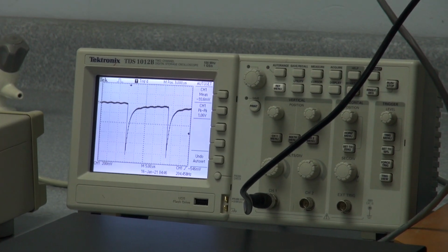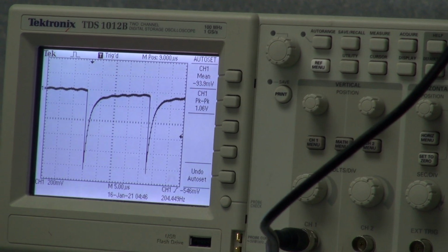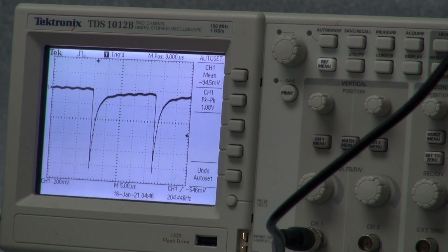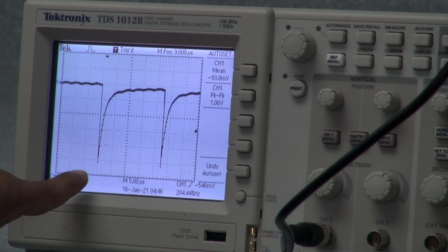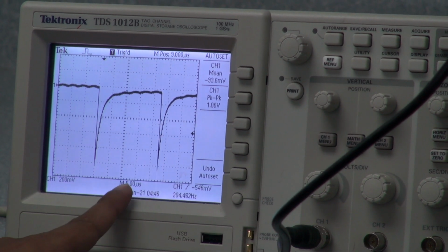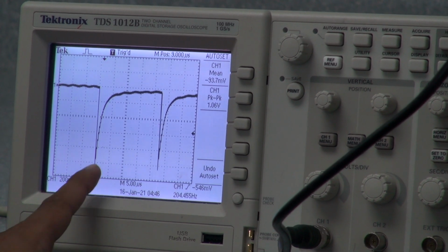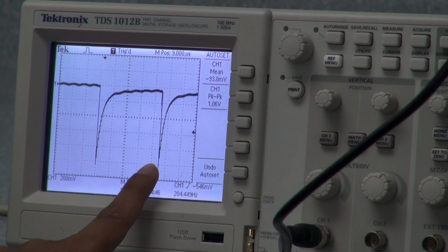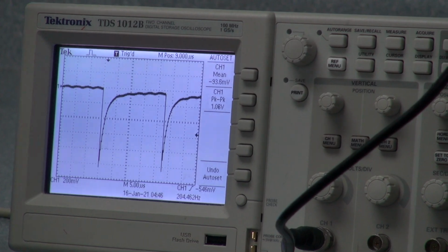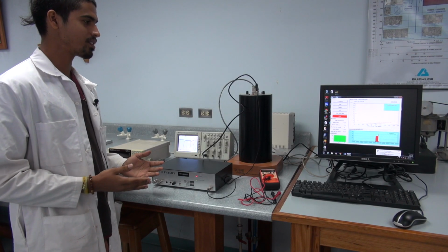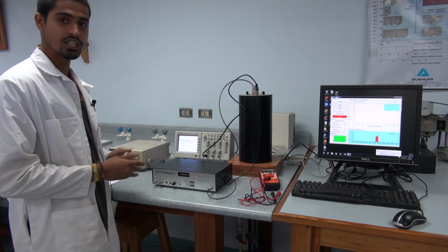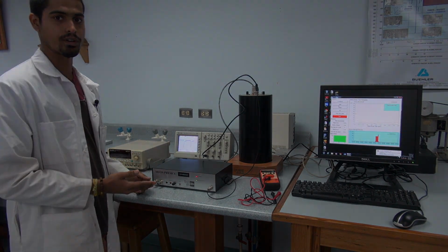We can see the linearity of the results between the software and the oscilloscope as we plotted in the graph previously. We can measure the time between the pulses on the oscilloscope. So right now it's set to 5 microseconds per division, and we have 4 2/5 of a division. So we can measure the time difference between the pulses, which can no longer be recorded on the software. Any larger time difference also will not be recorded.